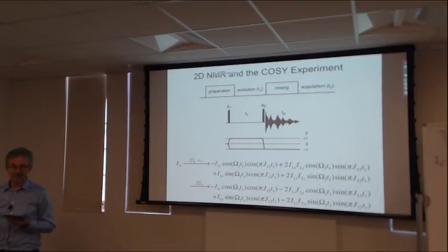In order to know whether you're rotating in this direction, you have to look down from the top and tell when I see the spot on this axis, do I next see it on this axis or next see it on the minus y axis? So you always need 2 points of reference to determine the sense of rotation. And you can easily go home and convince yourself of this by rotating a rolling pin or anything else you have on the axis. So that's been called quadrature detection for a very long time.